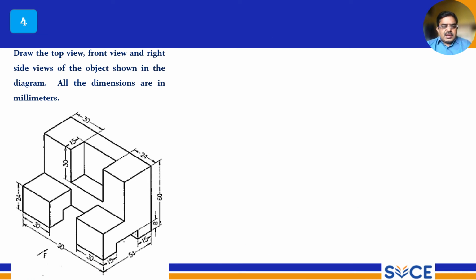So another machine component is given here. For this, the front view is possible. This is the arrowhead given for the front view, and the right side of the component is visible. So the right side view you have to draw on the left side, and then the top view is possible.